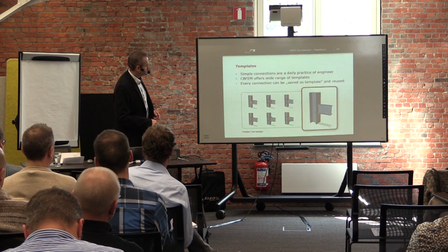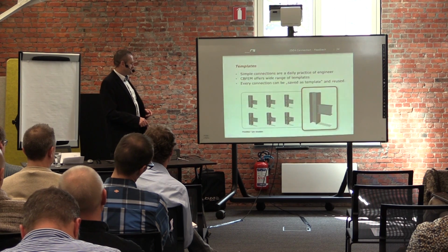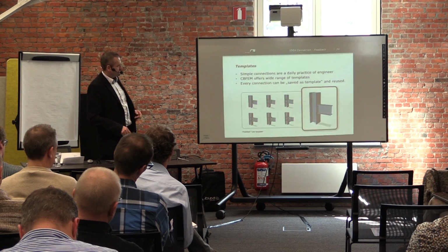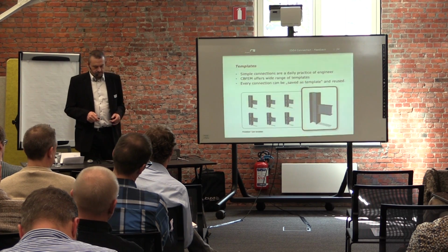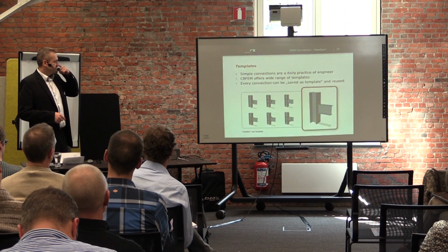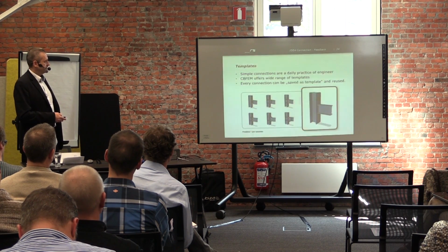So for such topology, we can use directly predefined templates for different kinds of connections. Like here, this is the fin plate. Here is the stub. I think this is welded. This is bolted with some haunches. This is bolted with one big haunch. So it means that for standard connections, you can use templates and be very fast and effective.